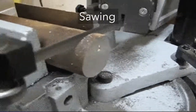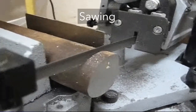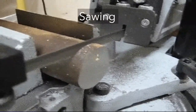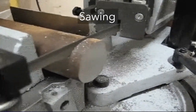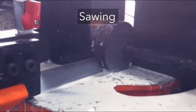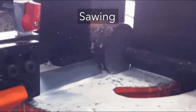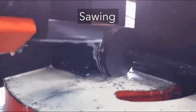Sawing is a process in which a narrow slit is cut into the work by a tool consisting of a series of narrowly spaced teeth. Sawing is normally used to separate the work part into two pieces or to cut off the unwanted portion of the part. These operations are often referred to as cut-off operations. Since many factories require cut-off operations at some point in the production sequence, sawing is an important manufacturing process.